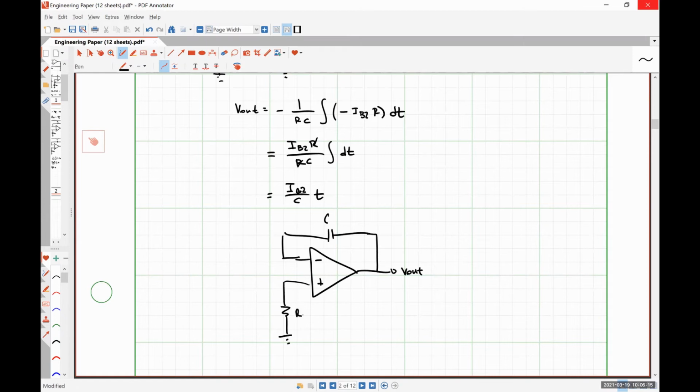Throw a resistor R here that is the same size as this resistor R. Our input bias current problem goes away, assuming that they are identically matched. If they are not identically matched, we put a resistor R2 here to correct for that.